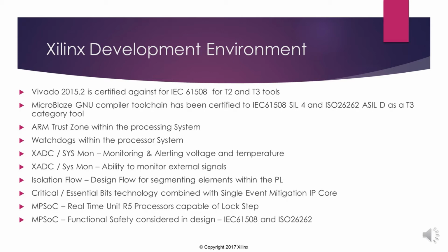Now what's really interesting is you think back to the global TMR and such like, and I was talking about how we would do the floor planning, then there are tools that Xilinx make available, such as the isolation flow, which is available for both Vivado and for ISE. And there's also a verification tool that allows us to verify that we've implemented that correctly.